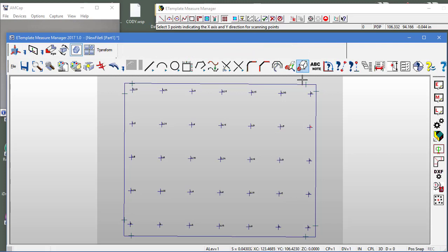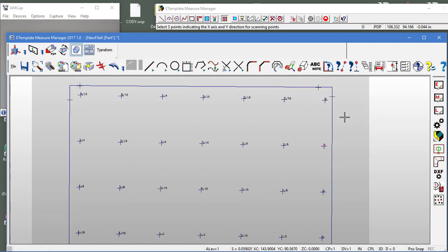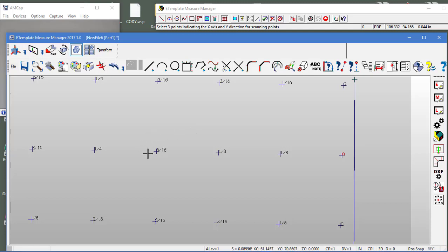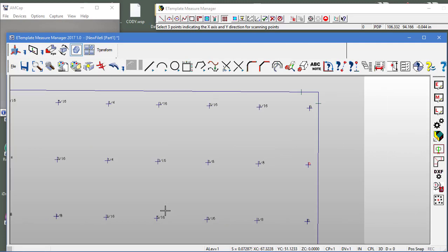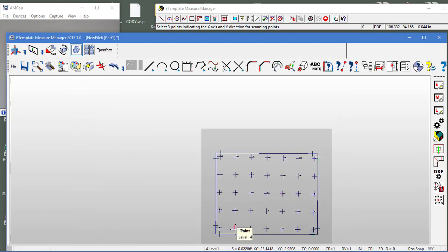And what it does is it analyzes it. The farthest out section of this wall is going to be a 0 in red. So here's our farthest out section of the wall right here. And if we zoom in a little bit, you can see other parts of the wall are as much as 3/16, even 5/16 below, lower than that section of the wall. So all of these zeros are at the same level, but this is the one that perhaps it's some 4 or 5 decimals out is the farthest out one.